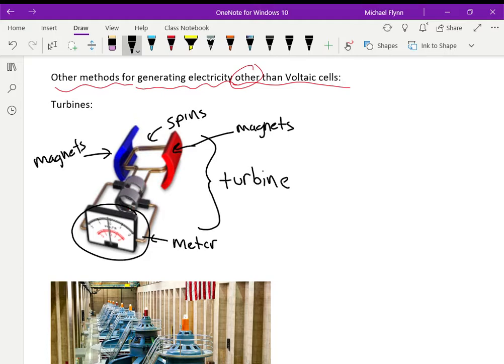These rings that you see are just to allow the rotating system to brush against a conductor. So there's a brush that brushes against it. We don't want our wires getting all twisted up. So we use these rotating rings with a metal brush that touches them. And the brush will carry the electricity to your stationary light bulb or whatever it is you're powering with your generator. And guys, this is the primary way that we generate electricity in society today. We spin turbines, okay? And when they spin, they produce electricity.